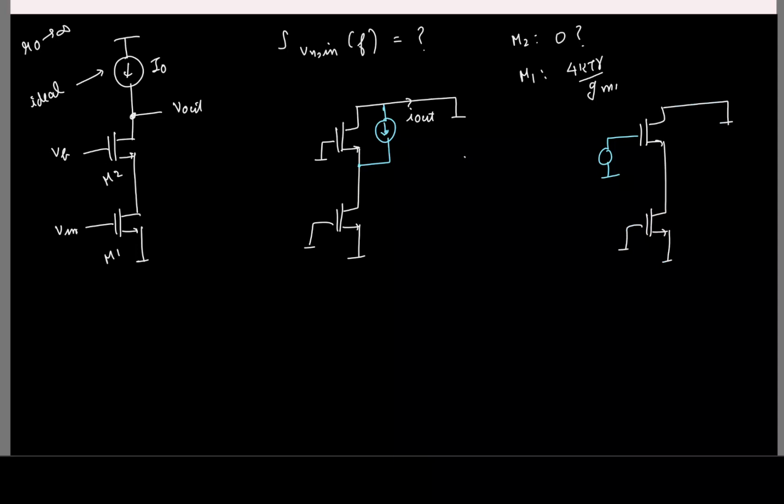So here I have assumed, I mean, what is the impedance looking down? I told R0 is infinity, so it's basically open. Okay, if this is basically open, if I call this current to be some IN2, what can you say about this current? That also has to be IN2, right? So this also IN2. So what about I out? 0.